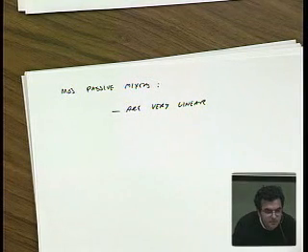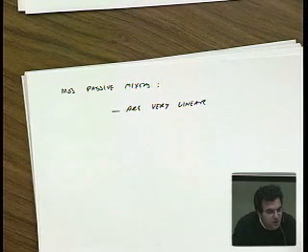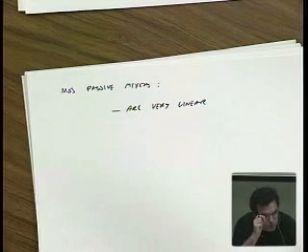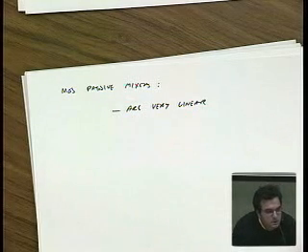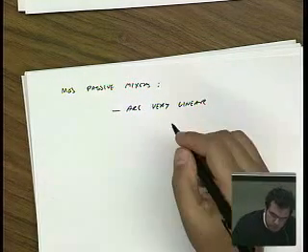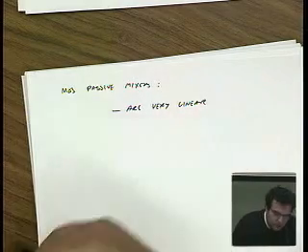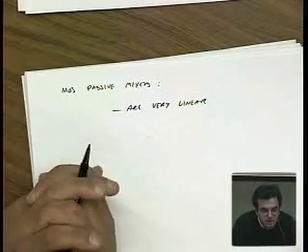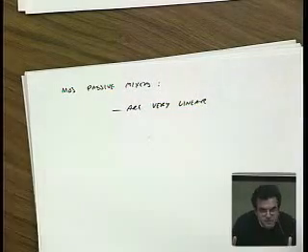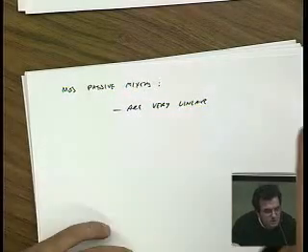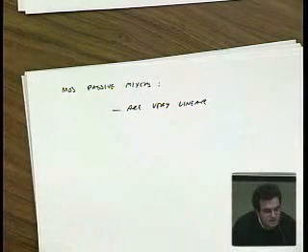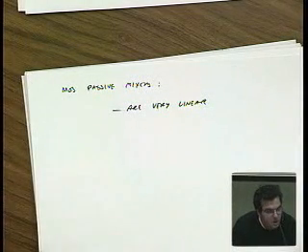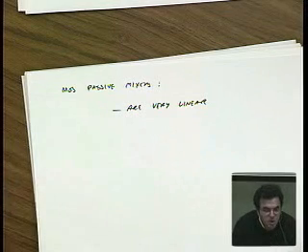R-on is very linear. That's right. R-on is a very small resistance. Even if it were nonlinear, it's a small contributor to the overall transfer function. So basically the fact that we're using the transistor as a switch means that it's going to be pretty linear, right? When it's off, it's just a linear capacitor. There's some nonlinear junction capacitance, but that's not too bad. And when it's on, basically it's just a small resistance.